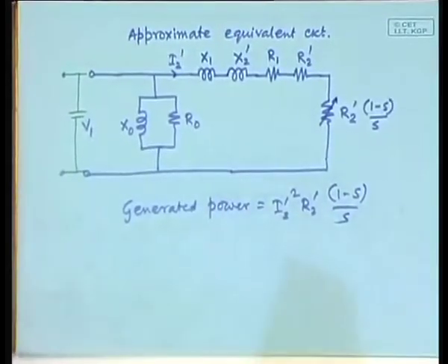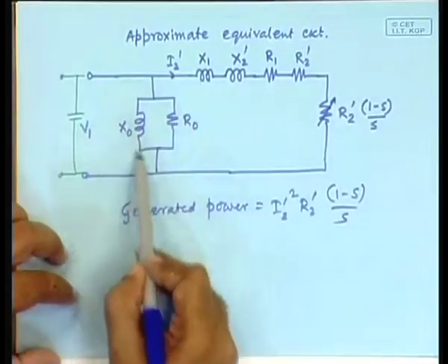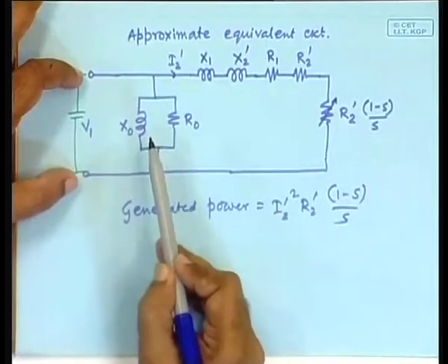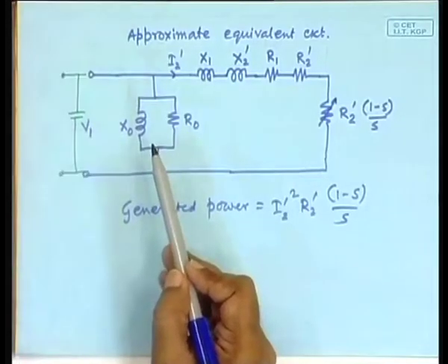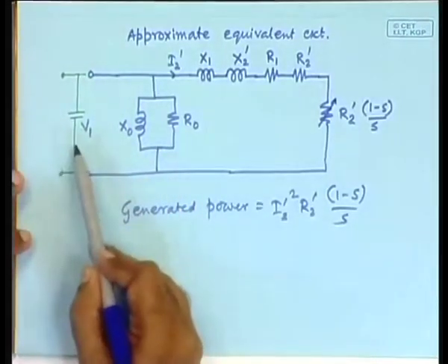Similar thing can happen in the induction machine also. What will happen? Well, in order to understand that, you have to look at this. See, here is a component that produces the magnetic field normally if you connect a voltage source here. And where does the reactive power come from? It comes from the grid. But supposing there is no grid, but you have connected a capacitor here, as I have shown here.